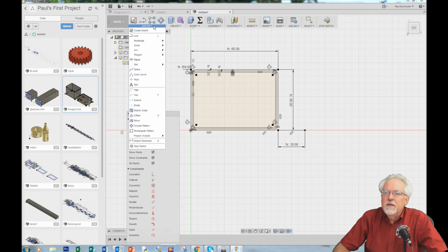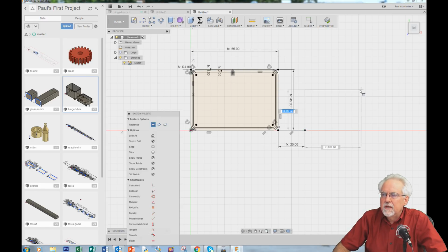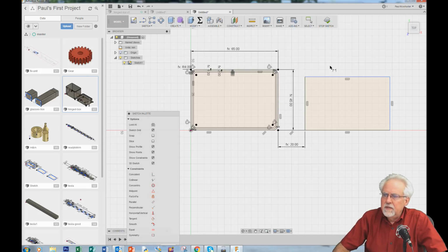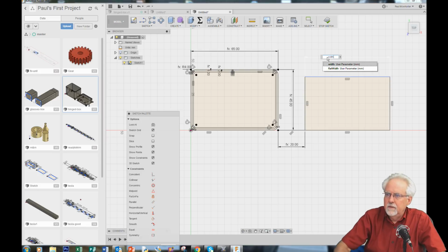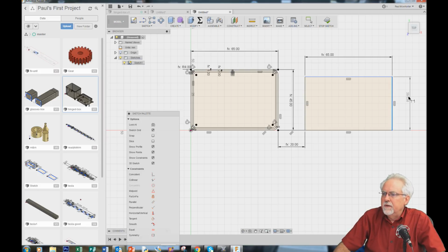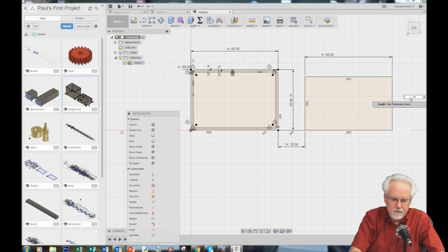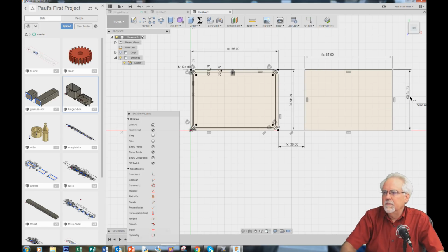So what do we want to do again? We want to make a rectangle. I'm going to go faster this time, okay? So we're going to make a rectangle. Click. What do we do? D for dimension. This was what? Width. All right. Enter, enter. This was what? This was length. Enter, enter. Boom. Now what do we do? We fillet the edges.